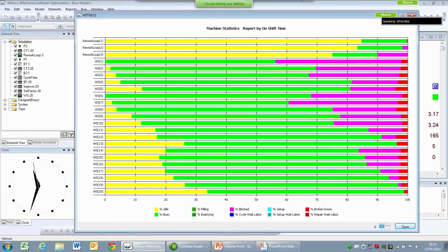But it's quite difficult from the other lines on this chart to work out exactly what the bottleneck on this line might be. That's because you have the busy time and the blocked time, and for the ones which hit the end here you don't know whether, if they were blocked a little bit less, their blocked time would turn into idle time, or whether it would turn into busy time. So they're all dependent upon each other to a certain extent, and for that reason it's quite hard to see what the bottleneck might be in this particular instance.